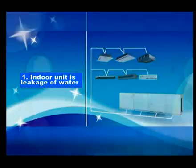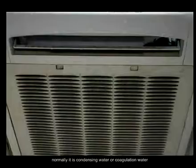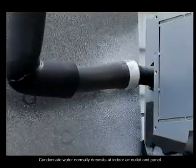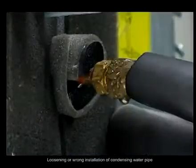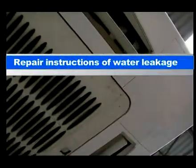Indoor unit water leakage. Check where the water leakage is from, whether it is condensing water or coagulation water. Condensate water normally deposits at the indoor air outlet and panel. Condensing water is normally caused by malfunction of the drainage pump, or loosening or wrong installation of the condensing water pipe. Repair instructions for water leakage.